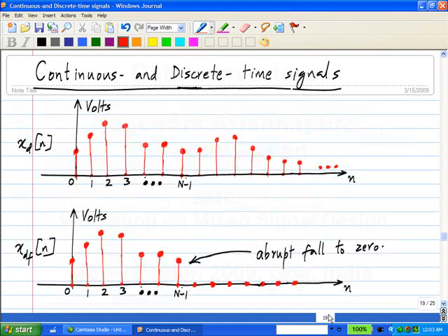So what is really happening here? The upper figure shows a signal that is running off to infinity, I mean an infinite number of samples. And the lower figure shows my modification, where I reduce all the samples beyond n to 0. So what happens? There is an abrupt change from here to here. There is a potential for an abrupt change. If the n minus 1 sample happens to be 0, there is no change, but it could be anything, right? So there is an abrupt change.